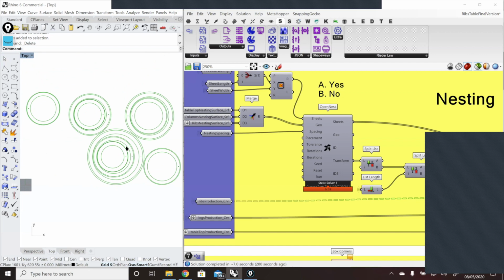Also, if you do curve containment, for example, if you test if points are in a curve, if you test in a NURBS curve, it's going to take a lot longer than a polyline, because a polyline basically is a series of lines, and it's very cheap to compute whether a point is on one side of a line or the other side. Yeah, a polyline is a list of points. Whereas a NURBS curve is an actual mathematical expression to create this representation of the curve. Yeah, so polylines are always good.